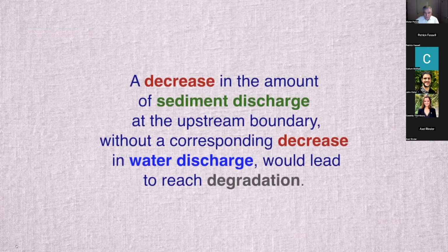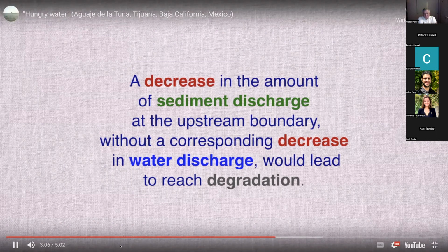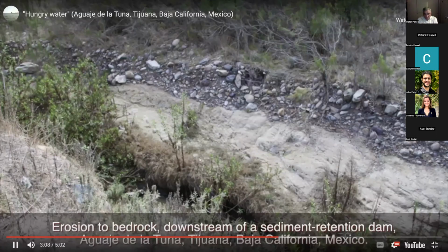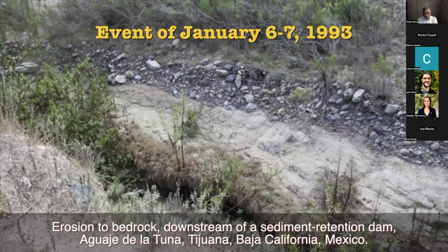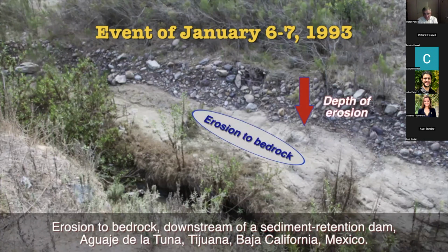The second case in particular merits careful consideration due to its significant practical implications. This situation usually happens downstream of a dam impoundment. The dam ponds the water and retains most of the sediment. The water subsequently released is typically almost devoid of bed material load. Therefore, it is "hungry water." This water will have the tendency to pick up bed material sediment as it moves downstream.